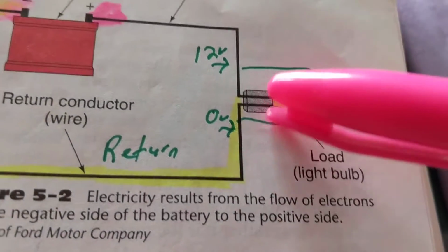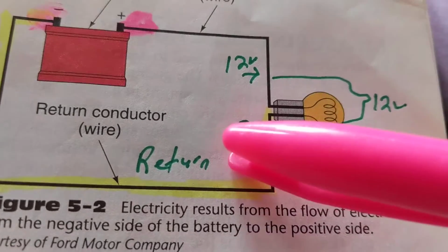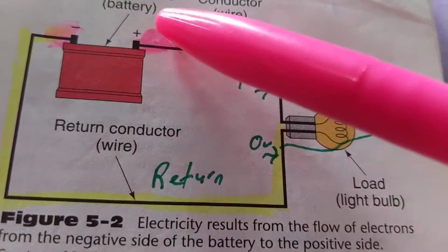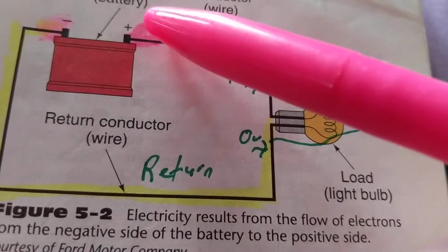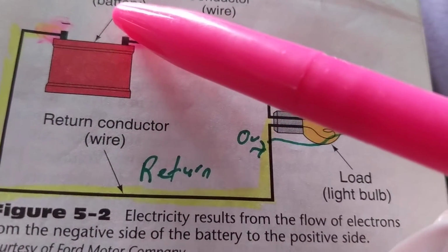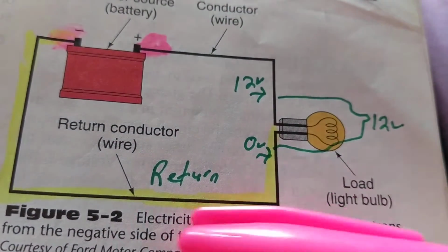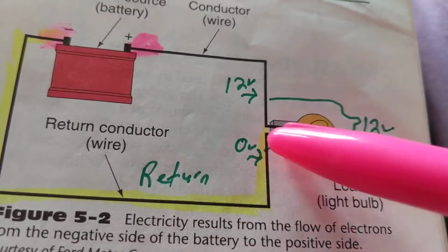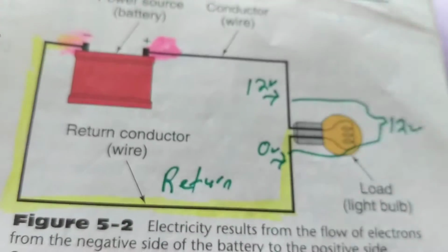What does he say? I'm sorry, that's not enough for me to light. That's why it's important. If you have it at the positive, you're going to lose 3 volts. Or whatever. Maybe 1 volt. Maybe half a volt. Whatever. You're going to lose voltage through it. If you have it at the negative, you're going to lose voltage because it's a resistance. You're going to lose at the ground. Same thing. He can't afford to lose more voltage at the ground path or at the positive path.